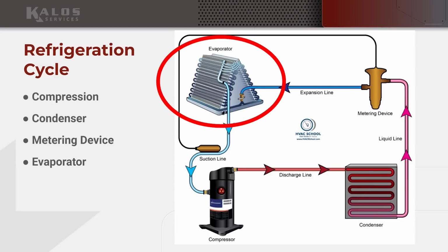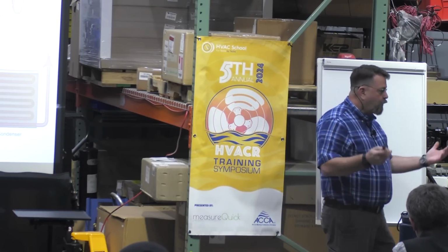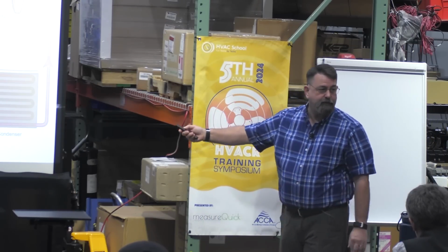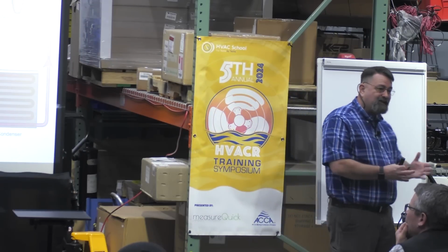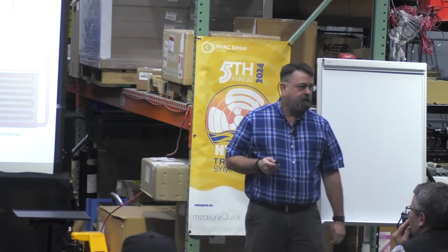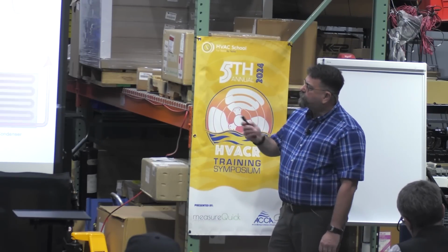Superheat? Yeah, this guy controls superheat. No difference. Why am I using superheat? To protect my compressors. It's the only reason. It's a loss of efficiency, but it's a safety I have to have built in, so I don't try to compress a liquid. We're doing exactly the same thing. That's exactly the same. No change there. Okay, so that's what refrigeration is.